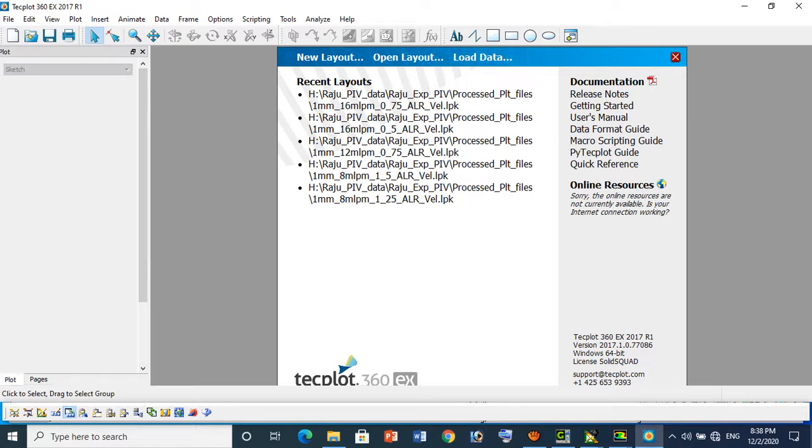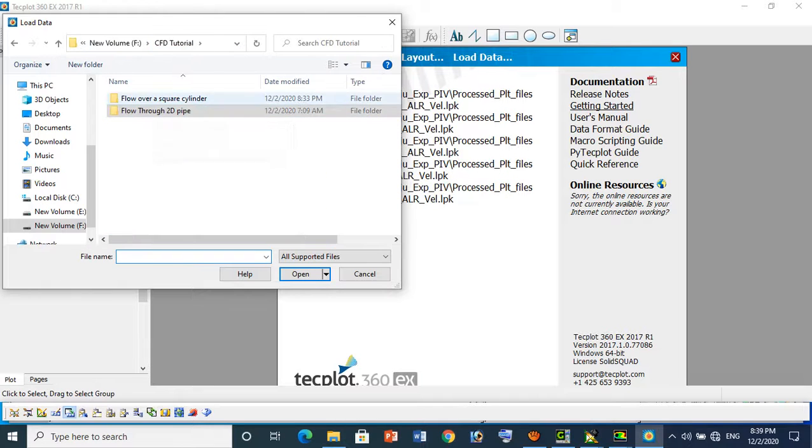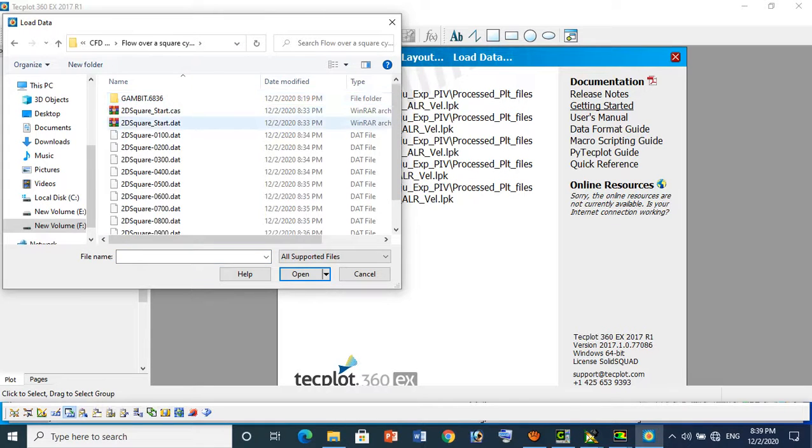If you want to improve the quality of the simulations, we need to consider many parameters such as grid convergence study, entrance length calculations, and quality meshing. We need to capture very accurately, which means we need to increase the cells nearer the body, using the inflation method. We have different options to do that. In later videos I will explain. These are just for understanding and learning purposes only.